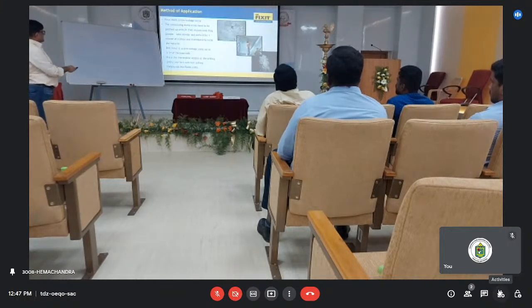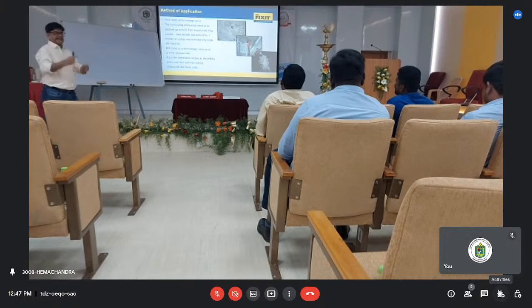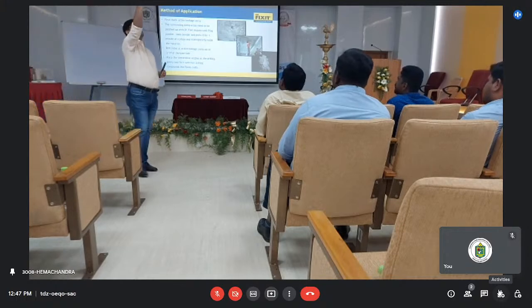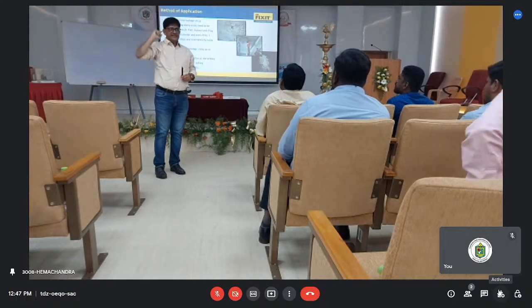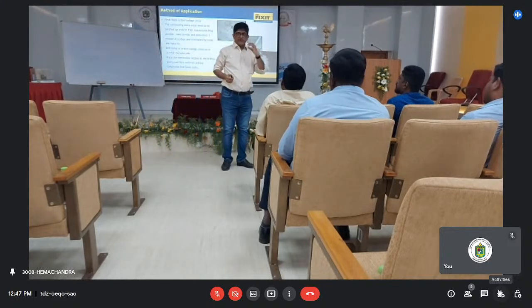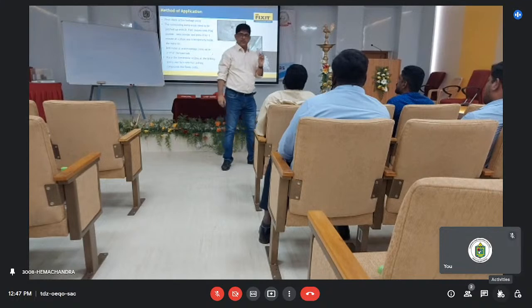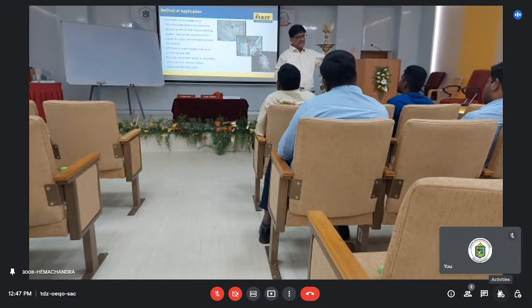How to do it first? Suppose this is the situation. Water or droplets are everywhere, water is coming from anywhere, right? Now first check which are the active sources. There may not be everything active. These areas have water continuously coming. Some areas here and there have small leaks. Okay, it can be there. Even if in the retaining wall area the water is coming from one side, I have to first channel out the water. First, we have to cut that area, drill that area. We have to put a pipe so that the water which is coming is channeled out. Other sections, let them be there. The major source of the water we have to channel out and throw it out.